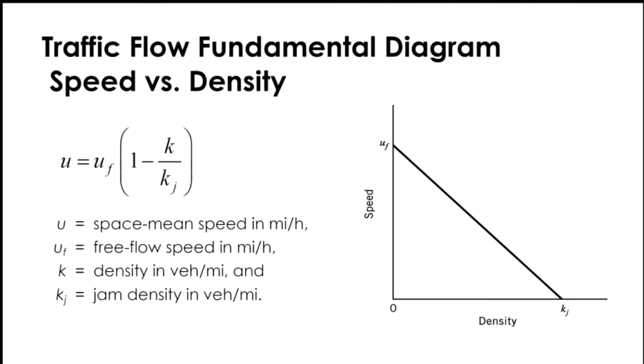Imagine we're looking at the speed density relationship. If you remember from previous slides from last week, the speed density relationship, if you plot it with real data, it will be very scattered. But we can approximate that relationship with a very simple linear relationship. And this is called actually Greenshields model. So Greenshields model is one of the very first models in traffic flow, which again, it's very simple. It assumes a linear relationship between a speed and density.